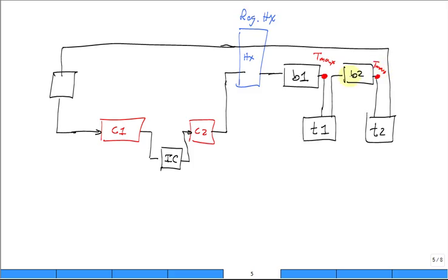By burning it again, you need more oxygen in there, so you couldn't have used all the oxygen. You still have to have some oxygen, mix some more fuel, have it heated up back to the maximum temperature, and boom, there you go. What you're trying to do is bring in more heat at high temperatures, good for efficiency. All right, so that's the intercooler and basically a reheat. This is going back. We have two burners reheating.